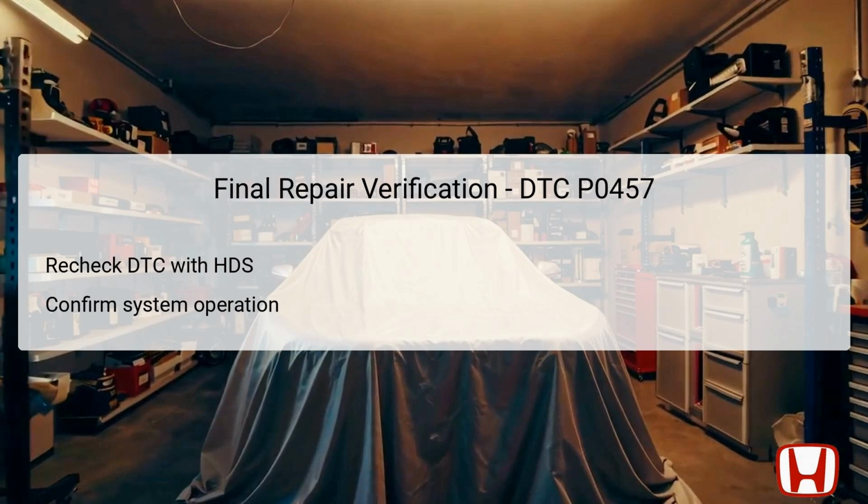Following the previous repairs made, especially if components have been replaced or adjusted, it's vital that all systems involved are confirmed operational. Successful verification means that the issues leading to the DTC have been resolved. Additionally, technicians should conduct further road tests where applicable to monitor the vehicle's performance and functionality over real operating conditions. This final check ensures that the problem is rectified, promoting confidence in the repair work done.